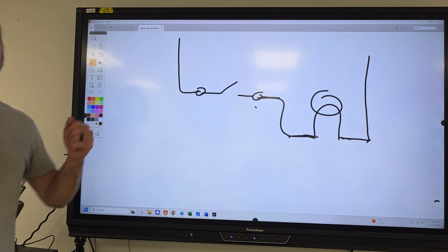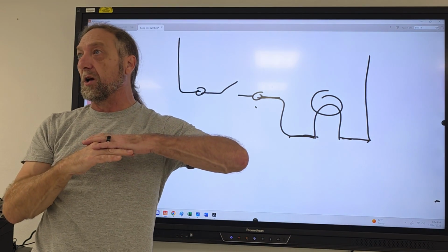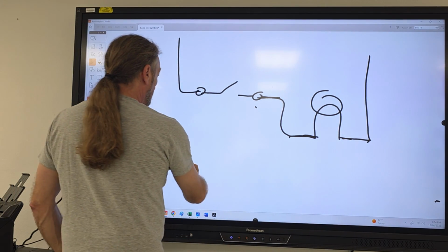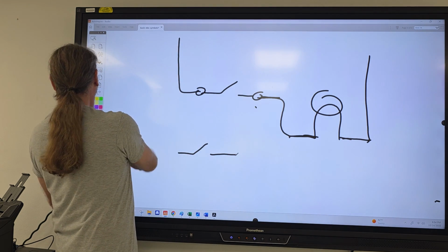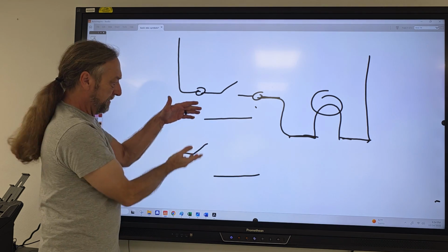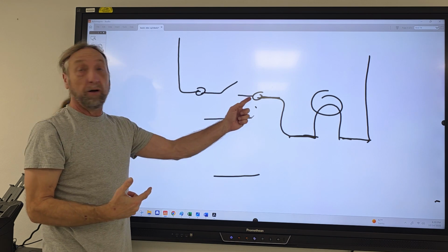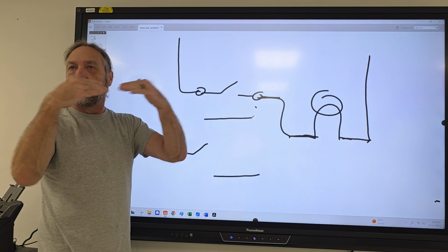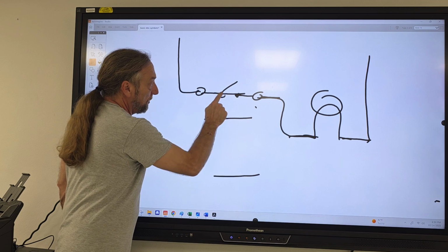You just have to know when the customer turns the machine on or manually turns that switch, that switch is going to close. But knowing the circuit, I've seen people take this second line and put it way over here, not even where the switch is, making it part of the switch, because they see it go like this and like this, and they don't realize that when the switch closes, this piece actually touches right here.